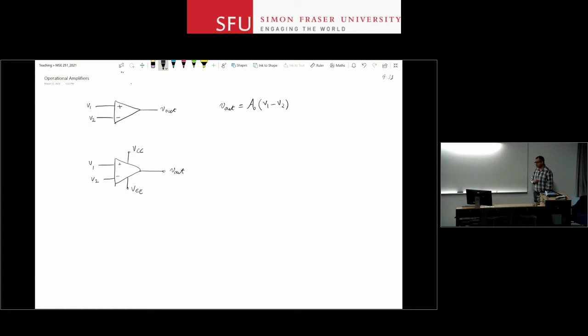Now, one quick note here, and we'll come back to how to select an op-amp hopefully by the end of this discussion. If you're choosing an op-amp for a single supply operation, make sure that you use a single supply op-amp, right? So not all op-amps are able to operate using, let's say, a ground connection for VEE and a positive signal on VCC. They are specially designed. Anyway, so at the very least, we know a practical op-amp has to have 5 pins, 2 for power supply and 3 for the signals.